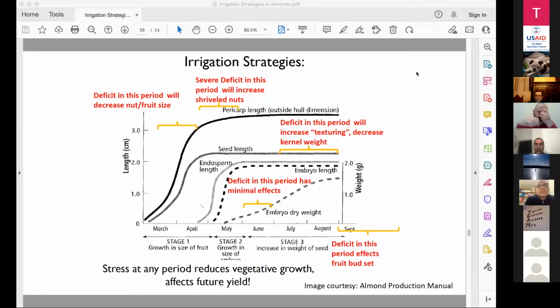We actually go by inches here in California, so that's what we translate to mostly. We apply about 1 inch of irrigation, and if we have less than 1/4 of an inch of water available, then we apply more.